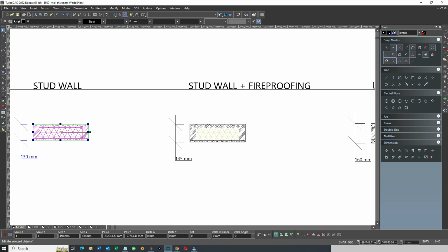And again, I'd rather the walls were represented slightly thicker than the other way around, because if the builder is trying to fit a door and he just can't get it in because he's cut by 10 or 15 mil, you're starting to cut down fireproof doors and so on. So that's not good. So it's better to be oversized with the walls than under.